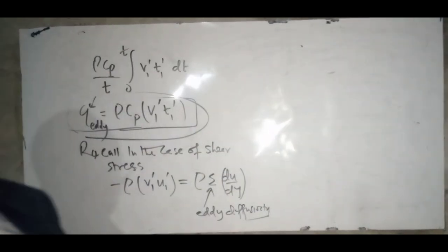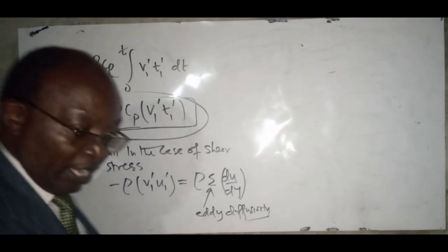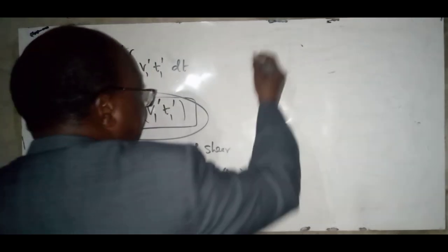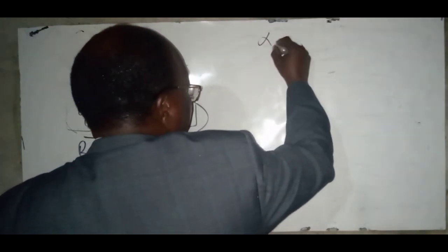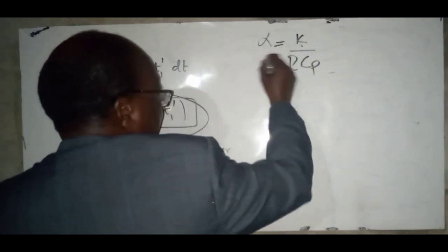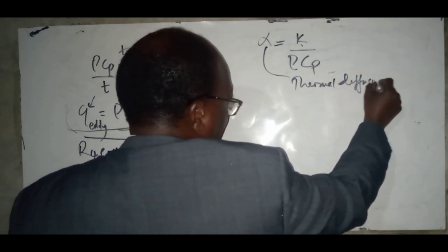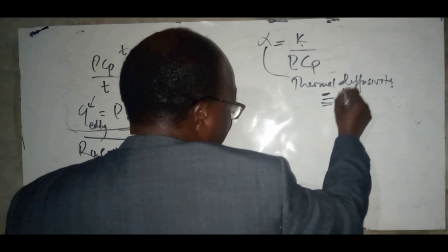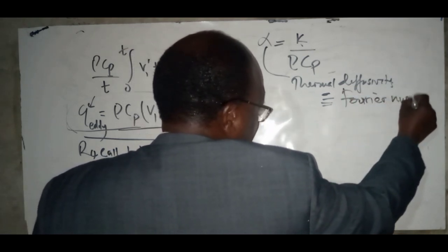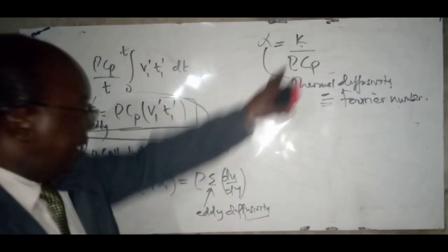If we remind ourselves, like we had seen derived in the earlier lectures, where we derived the thermal diffusivity, which was part of the Fourier number, we had said that alpha, the thermal diffusivity, was K over rho Cp. And this, remember, was in the Fourier number, where we derived the Fourier number and Biot number. And so we can bring that in there.